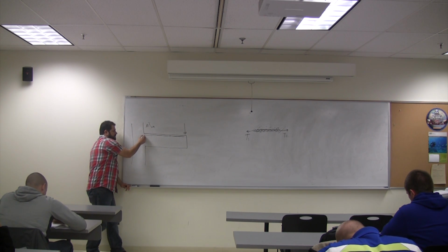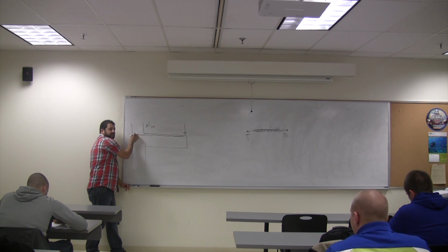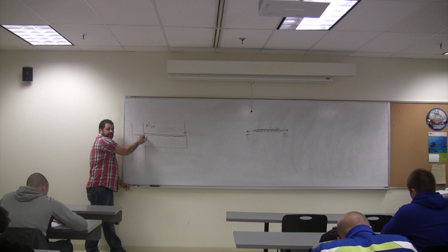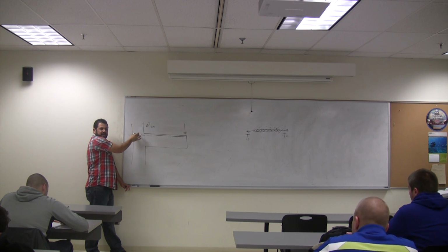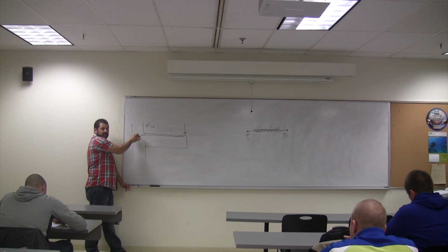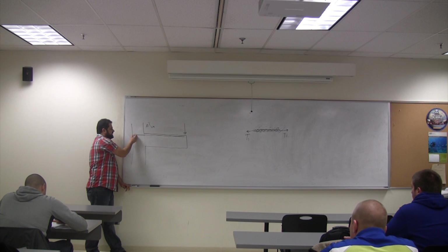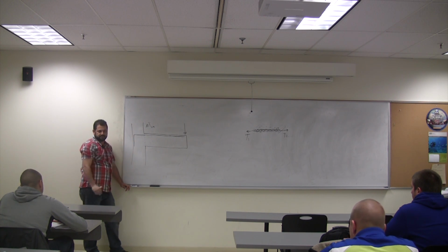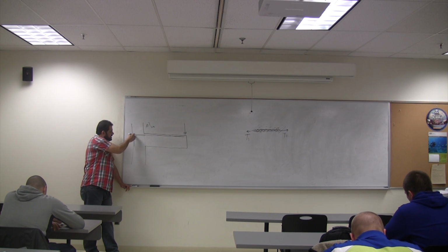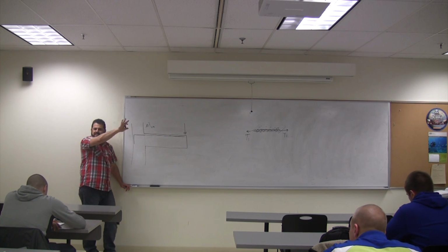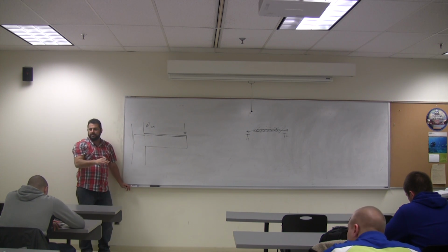So they must be embedded in here so that this length can give me enough to develop a Fy in here. Now, sometimes the support is narrow or small and will not give you enough length if you do straight bars in tension. So you see the hook. This is a standard 90-degree hook. Could be 180. These are standard values for how much you go, how much the turn. They will be fabricated for you.